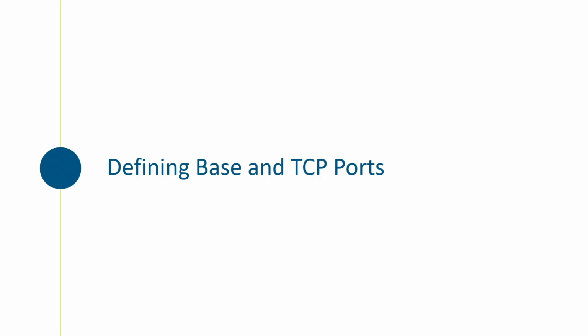And what that effectively does is allows you to say that I want to put a robot in a particular pedestal area, tell me where it can go. And it will actually do a nice little study where it adds different squares, shows you where it's a good one, where there's a collision, where it can reach and where it can't. And those aren't as intuitive as you might think, right? In the center of a table you might think you can get to where you need to when you have to reach a bin and then you have to reach where the part's going into the fixture. But sometimes those joints can kind of handcuff you and you're actually too close to something. I can't grab my own elbow with my right hand. That's just something I can't do. So it's really great to have these automated tools to be able to control that for you.